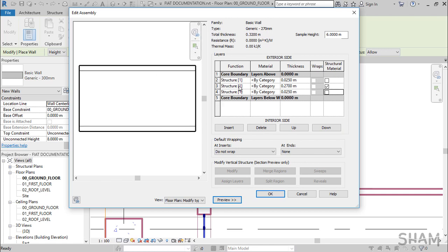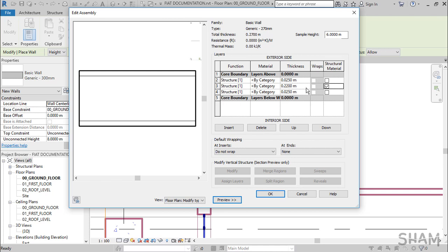Now one thing we need to fix is its total thickness. It should come out to be 270 mm, but ours is a bit larger because we already added the thickness for plastering. Well, the good thing about Revit is you can do your calculations inside it. To do that, select this value and enter a numerical calculation, but start with an equal sign. The two values are the thickness of the plaster on both sides. Then hit Enter, and Revit will give the value as such.